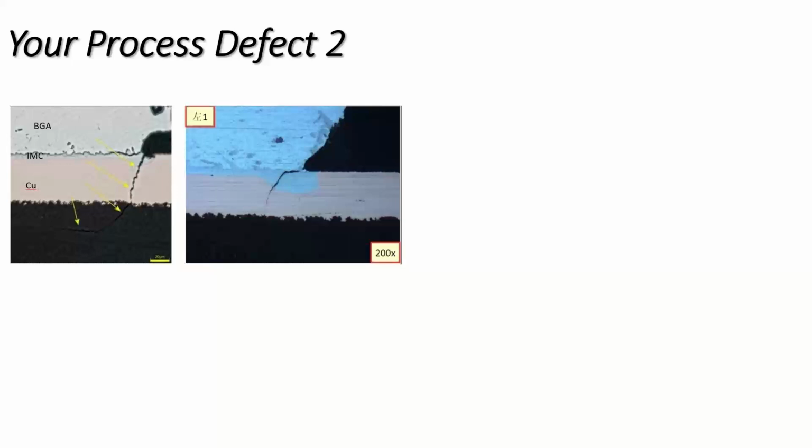But if you're going to conformally coat a board, it's perfectly reasonable to conformally coat the whole board, but not necessarily conformally coat underneath the BGAs. And some companies do that as part of their practice, so they try and eliminate that as a possibility. But if you know the material has the same expansion coefficient, then it's less likely to be an issue.